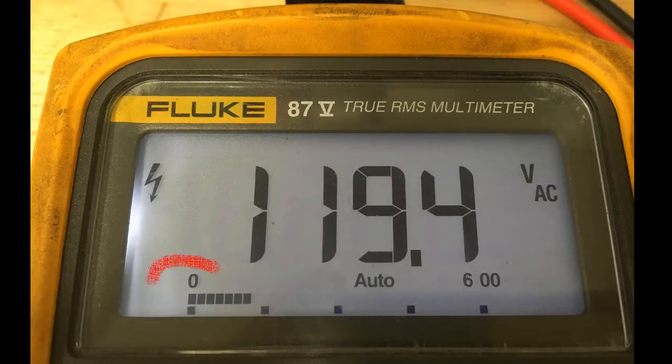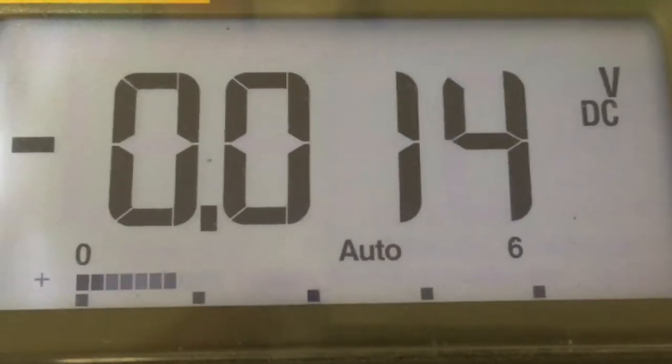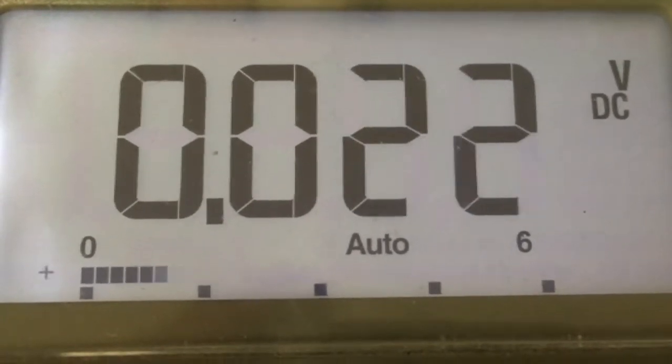For most of the measurement modes, an analog bar graph on the bottom of the screen will represent the measured value relative to the range setting. This bar graph will update 10 times faster than the digital display. When the digital display is rapidly flickering between values, this analog bar can be used to gather a better understanding.